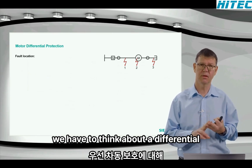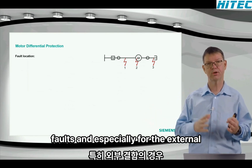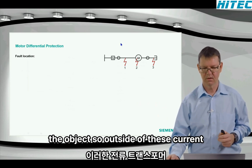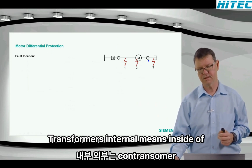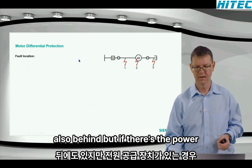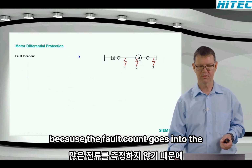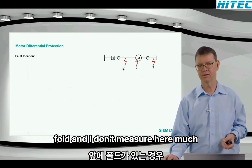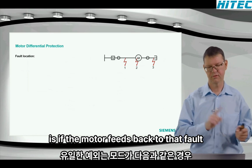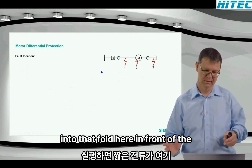First of all, we have to think about a differential protection. It distinguishes internal and external faults, and especially for the external faults, we think about the region behind the object. So outside of these current transformers, internal means inside of the current transformers, external means normally, of course, also in front, but also behind. But if there's the power supply from the left, I will not see some current if there's a fault in front, because the fault current goes into the fault and I don't measure here much current on that side. The only exception is if the motor feeds back to that fault, if the motor is running, then I get also a short current going into that fault here in front of the motor.